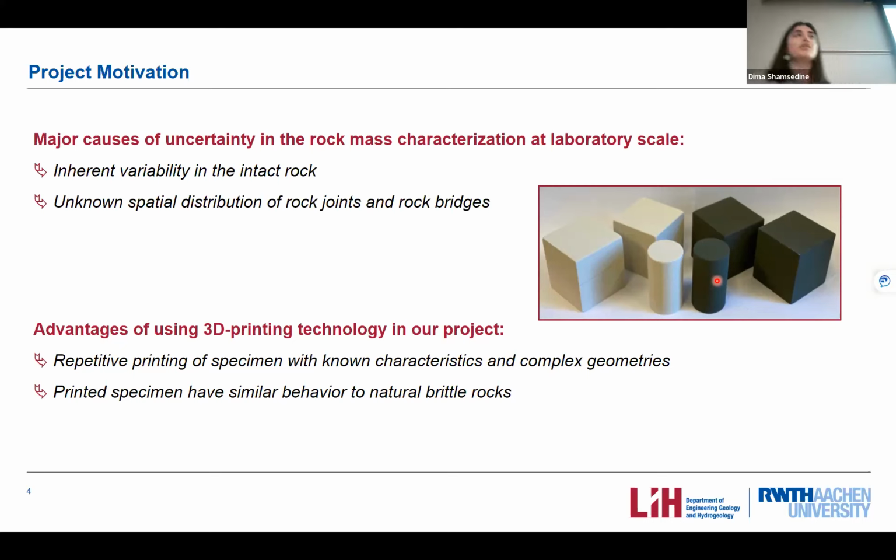Moreover, the presence of micro cracks inside the intact material itself, and the mineralogical heterogeneity, which is inherent in the intact material, adds an extra challenge to the laboratory testing, in which we will have non-repetitive laboratory testing when we are doing our tests. We have errors in the laboratory results, and the coefficient of variation among laboratory test results on natural rocks can reach higher than 25%. So all this leads us to adopt the 3D printing technology.